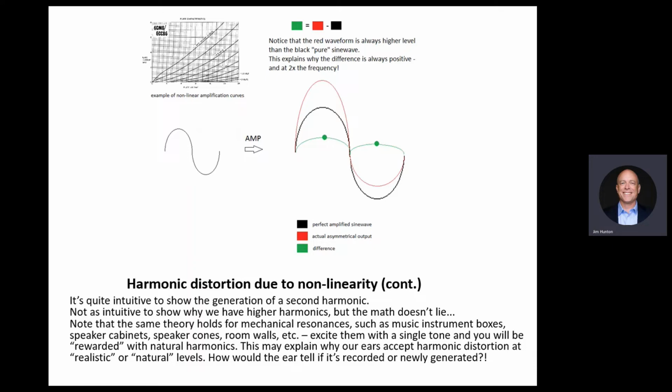The fix to that, like everybody will tell you, is to use a complementary circuit. One device amplifies more when the signal goes up, the other device amplifies more when the signal goes down. Eventually, you compensate for it. Yes, that will eliminate second harmonic, and that's a push-pull circuit in tubes or a complementary circuit for transistors. However, 2 devices are not one. You have to make the 2 of them work together. The curves of one have to match the curves of the other. Well, what if they're not coming from the same batch, the same manufacturer? There are so many issues with that.